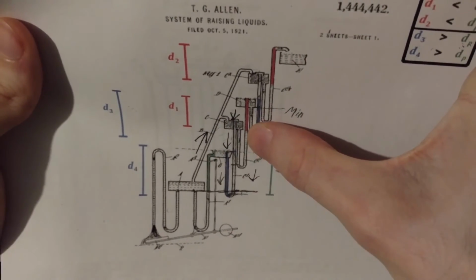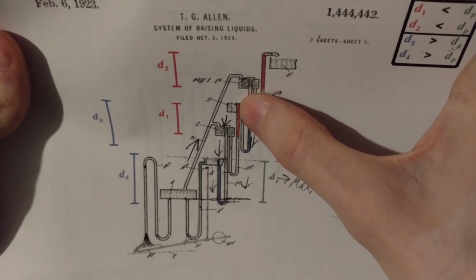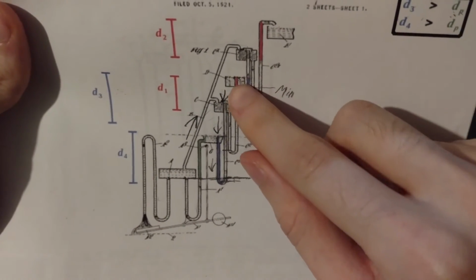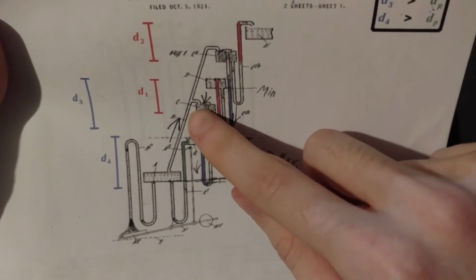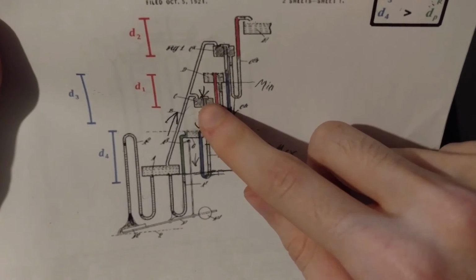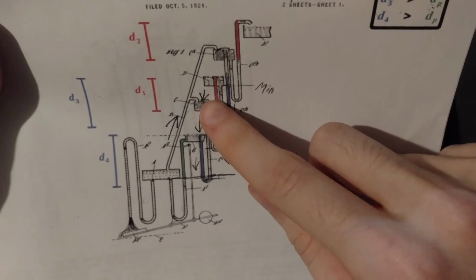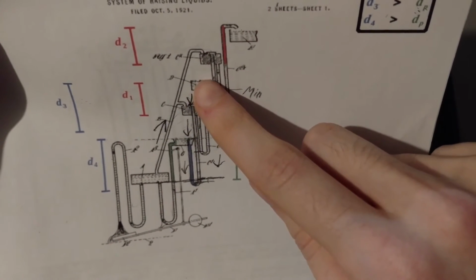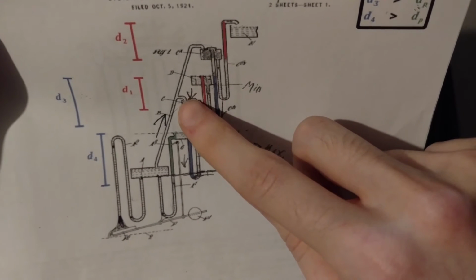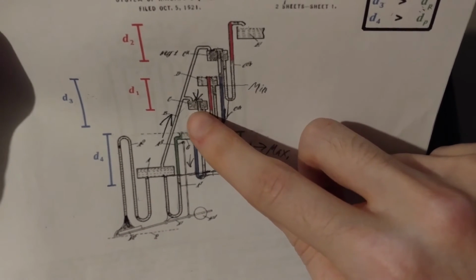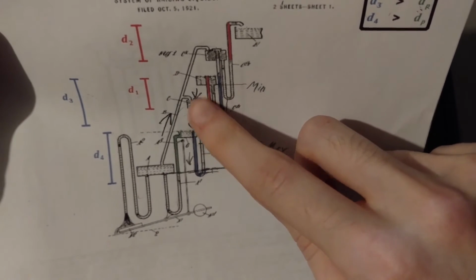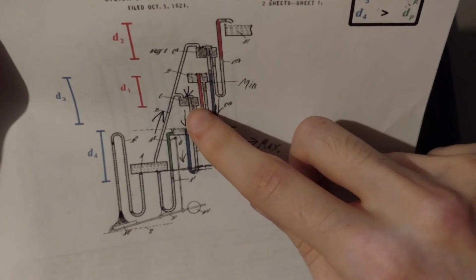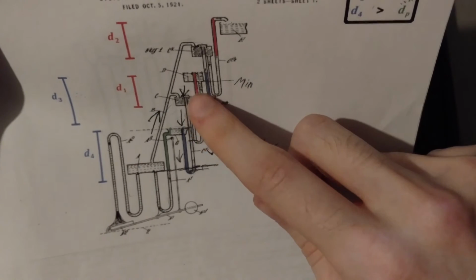Let me show you. The water is being pushed up that red tube, and your back pressure, the resistance against that water, is going to start where that water line is, and it's going to end at the end of that tube. So the distance between here and here, going all the way down to the bottom of the tank, is why I have the red ending there. So that's going to be your maximum back pressure.